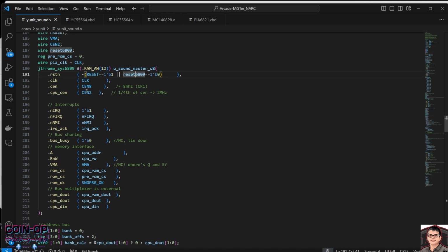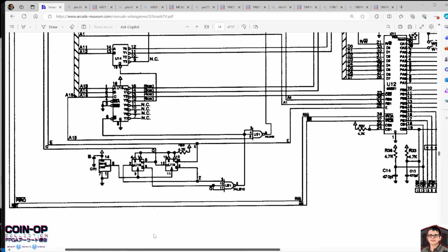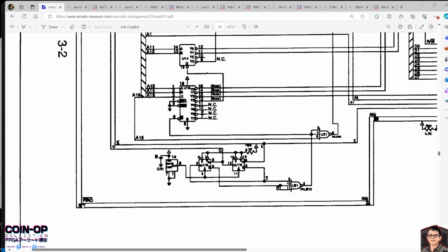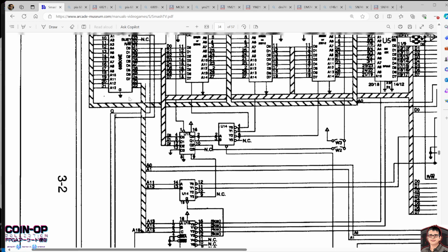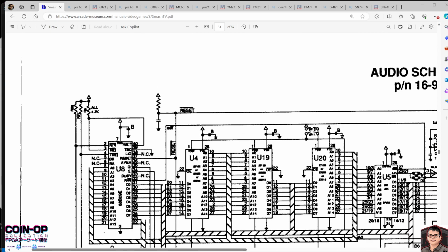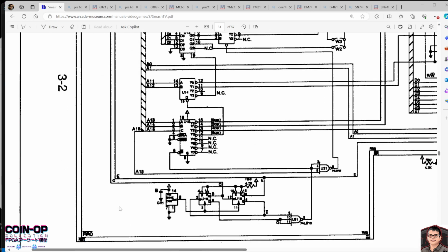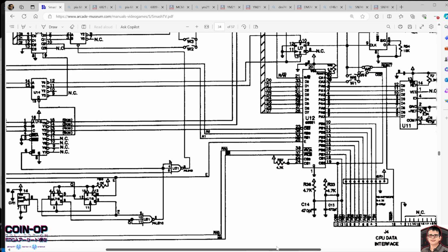Okay, and then we have the clock enables that we saw above, and then we have the interrupts, the fast interrupt and the NMI. Those appear as pins over here. You see there's FIRQ, which is fast interrupt request, and NMI. They are wired directly into the NMI and fast interrupt request, and they go straight across into the PIA.